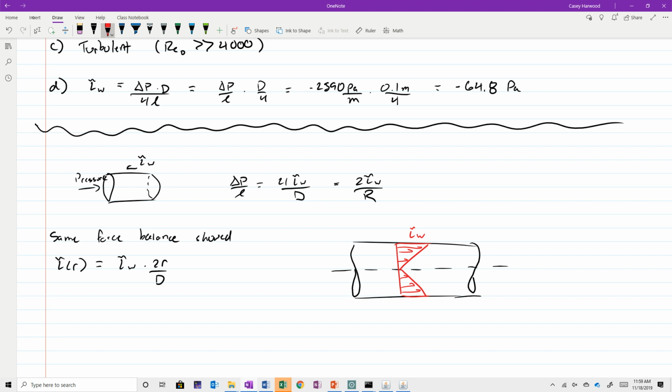Great. Problem is that doesn't work that well for flows of engineering significance. Flow is not that often laminar unless you're talking about pumping asphalt or molasses or corn syrup. When you're talking about pumping air or water through large-scale engineered piping distribution networks, it's typically going to be turbulent.